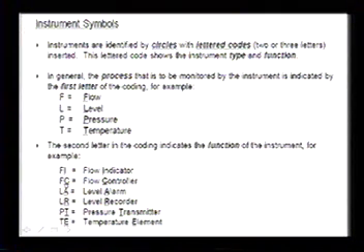FC is a flow controller. What is your flow controller? In this example, your flow controller is the PLC, right? But you can also have mechanical flow controllers, and those work very well if they're set up right. And then you got your LA, which is level alarm. LR, level recorder. PT, pressure transmitter.